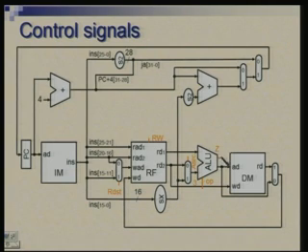Then a status output which will come from ALU, I am labeling it as Z, standing for 0. So, it is a comparison of the 2 operands from the point of view of BEQ instruction. Comparison, you recall, was done by doing subtraction and checking if the result is 0. So, that is why I have labeled it as Z. This is not an input, this is an output, this is a status and others are control.